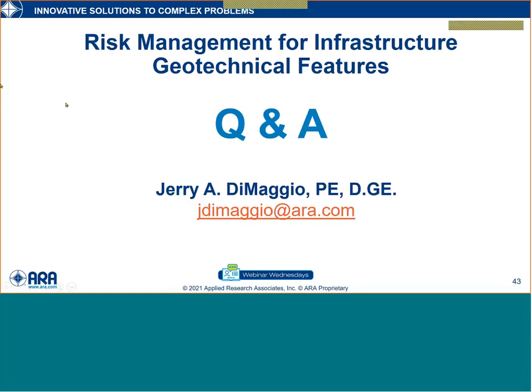Thank you, Jerry. Here's a question from Jose, who states, what's your best advice for researchers looking at developing retaining wall deterioration models? So I'm going to use my trump card and say it depends, Jose. It depends on what kind of retaining wall it is, and it depends on the deterioration mechanism that you're evaluating. If, for example, it was a mechanically stabilized earth wall, a reinforced stone wall that used metallic reinforcements, then the deterioration mechanism that most people are focused on would be corrosion. But that's only one deterioration mechanism. So I go back to my short answer, it really depends. You have to look at the wall, look at the permanent service life requirements, and look at all the possible mechanisms that could adversely affect the performance of the wall.